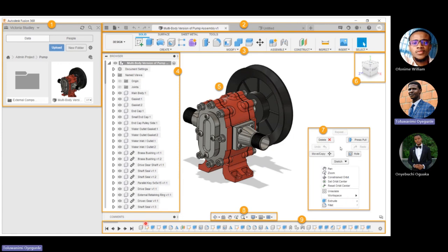So all these things you see here from start to finish are recording the processes that built up this assembly. This is only possible if you are using parametric mode. If it's direct modeling or direct editing mode, you won't find any of these things here. Direct editing is when you are just trying to design without using a parametric kind of function. Do you understand? So those are the kinds of modes you find in Fusion.